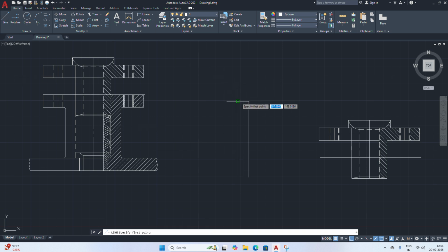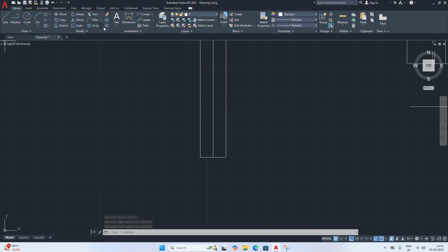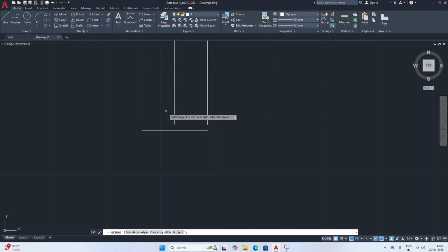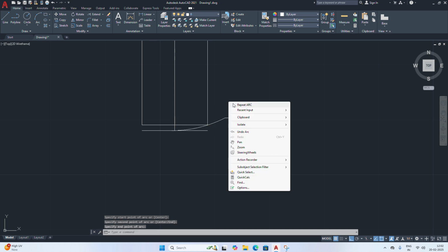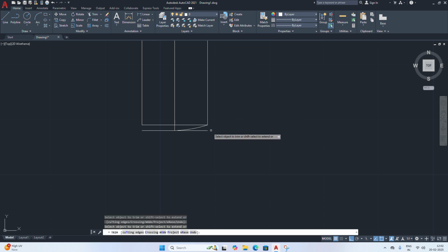Okay, now just close this one, and this side also. Enter. Now just offset this line through 1 mm. Okay, now we'll extend this line to meet there. Now we'll draw a curve like this. We'll just draw a line somewhere here, just a point. Now we'll use arc. Okay, 3-point arc, starting from here, this point and this end point, so that we'll get a curve there. Now we'll delete this line. Trim, just trim that, trim this curve and this line, enter, trim this side also.